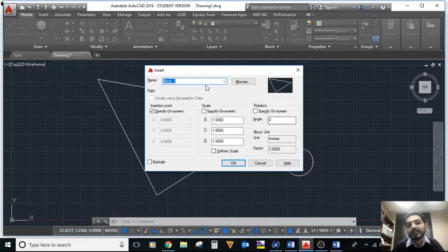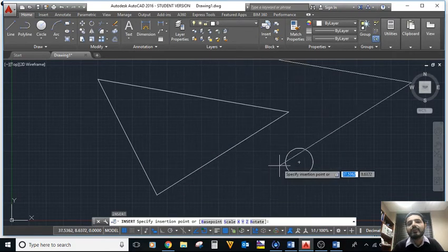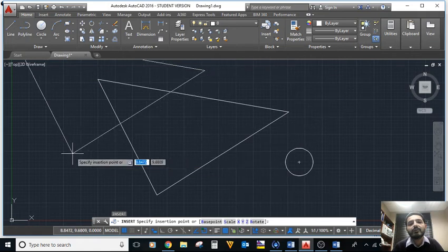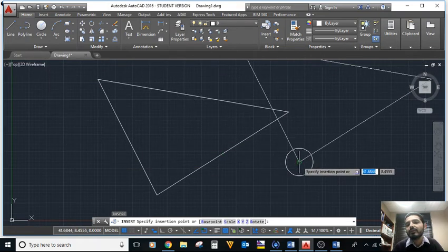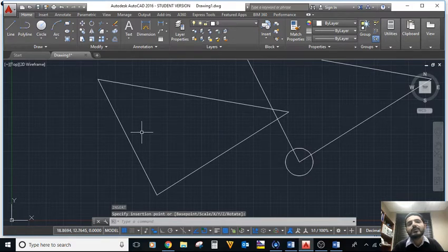And the nice thing here, it shows you all the types of blocks, because here we did object 1, we did block 1, so it looks like yes, we did create the two of them. So those are the two objects, and what you do is just click OK, and now it's going to ask you where you are going to put that block. So hitting OK again, see, this is the base point. All you need to do now is select any point where you need to put it, and you put it there and you inserted that.